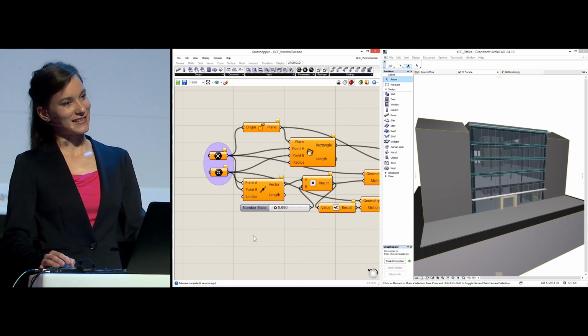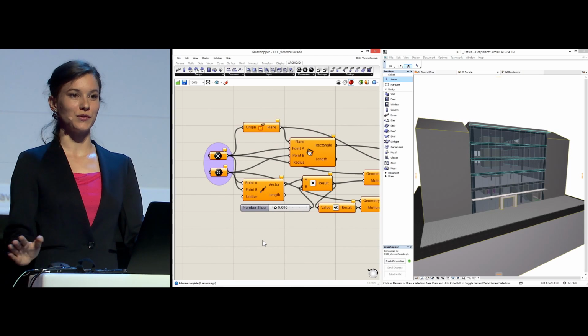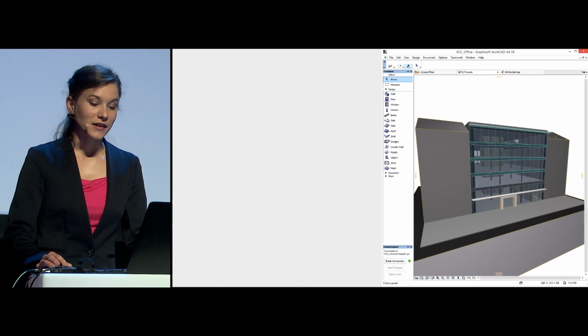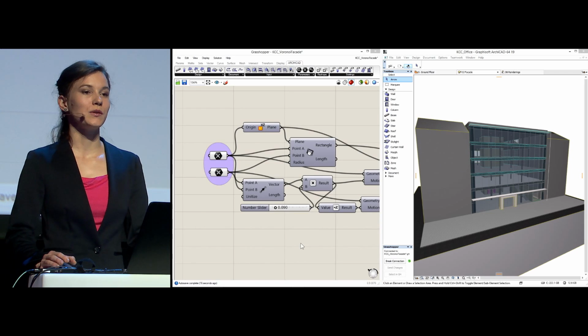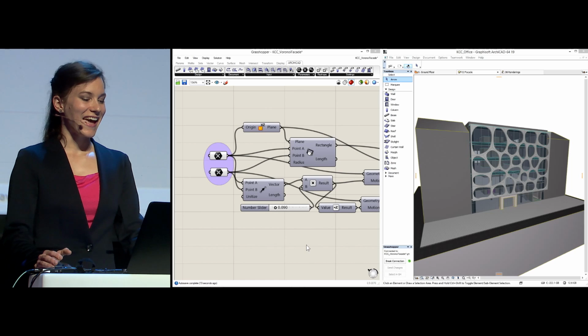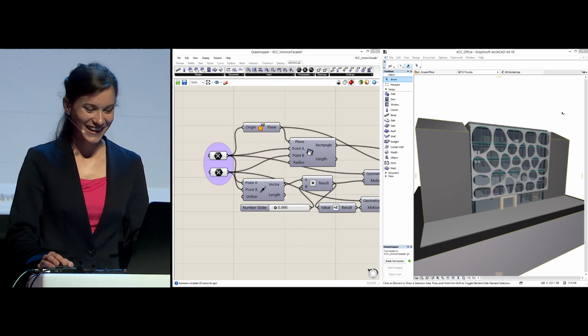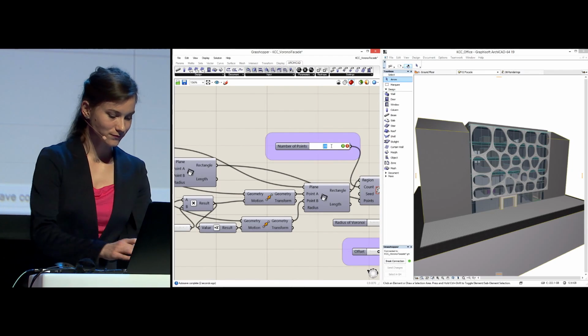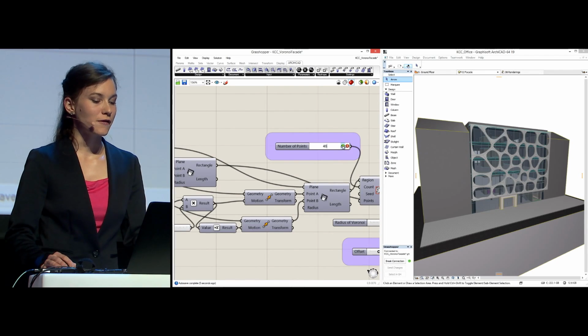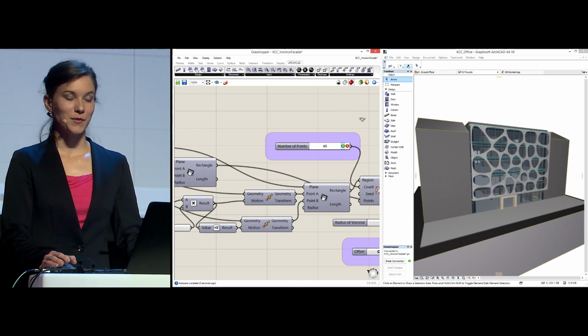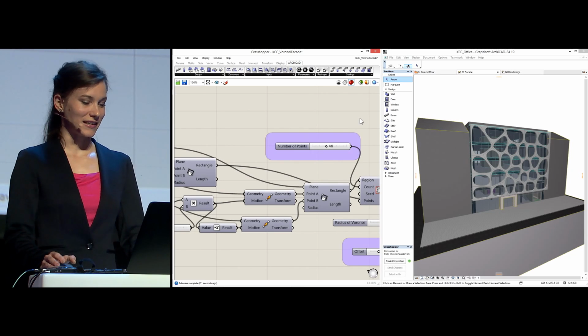Well, I have created the Grasshopper code, but in this case, I won't use Rhino at all, because I only need to pick 2 coordinates from my ARCHICAD project. So remember, I am now referencing ARCHICAD geometry. And soon after I define those coordinates, the new shading system will appear in ARCHICAD. And with the help of our parameters here, we can fine-tune the pattern anytime, again saving a huge amount of design iteration process.